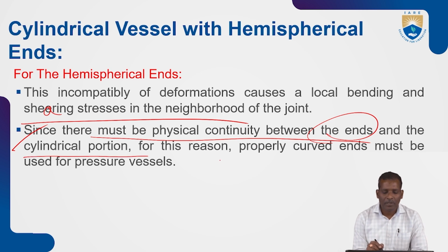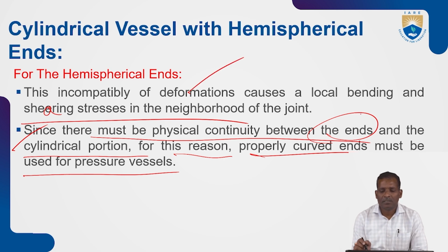For this reason, properly curved ends must be used for pressure vessels. This incompatibility of deformations causes local bending and shearing stresses.